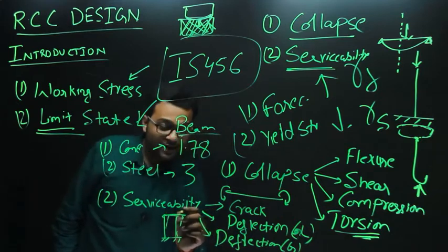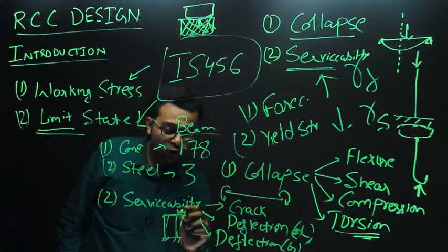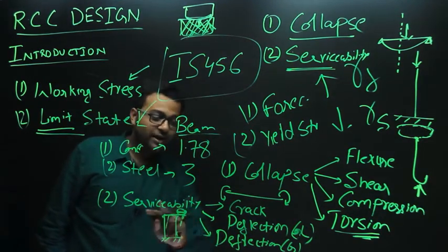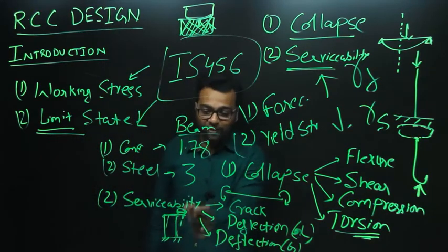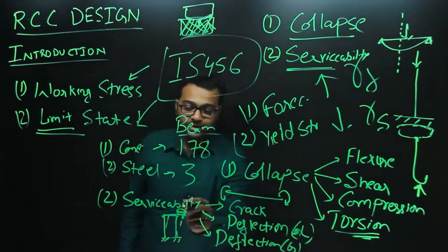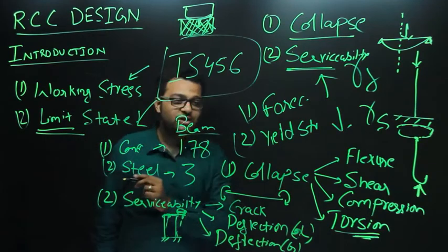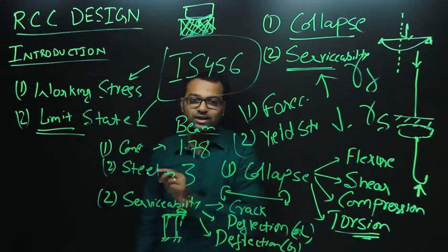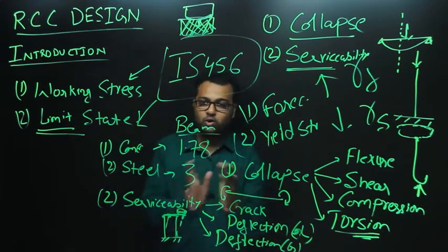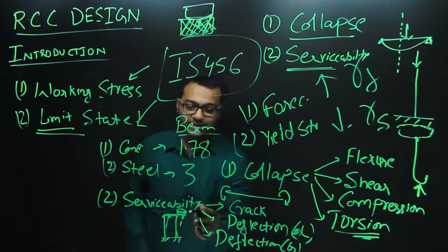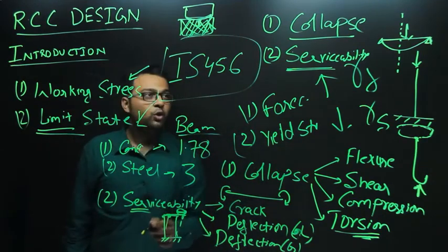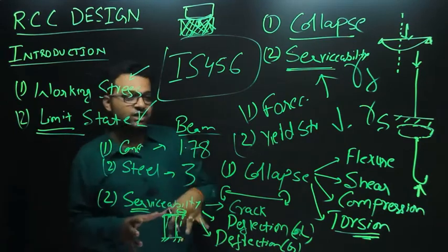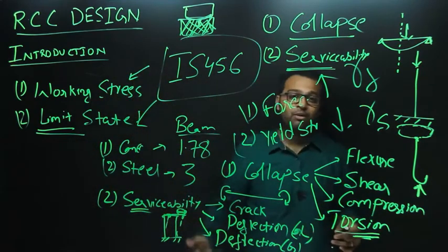Although the deflection happening at the topmost story is not affecting the overall structure, it is affecting the person who is residing in that story. The person is not feeling comfortable because of the sway. So that is again a serviceability failure. We do not want a person residing in the building to have uncomfortable feelings.